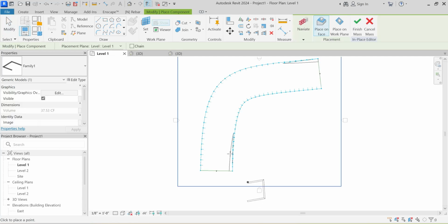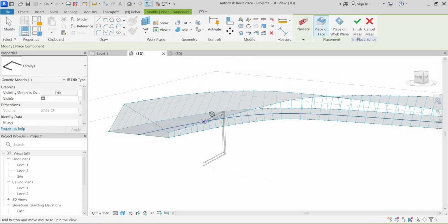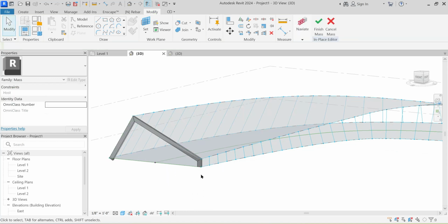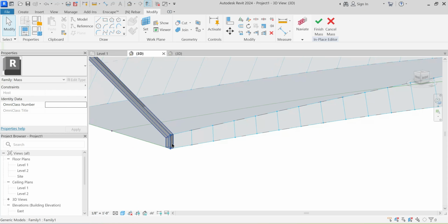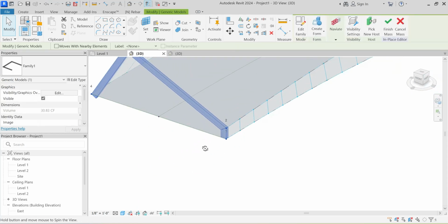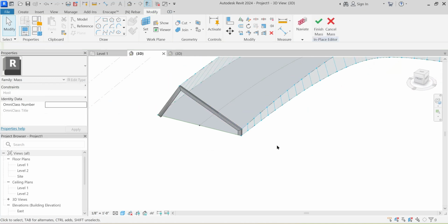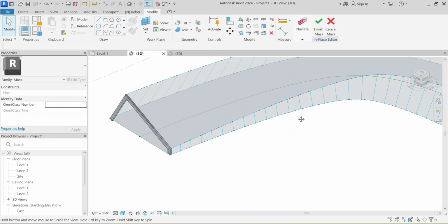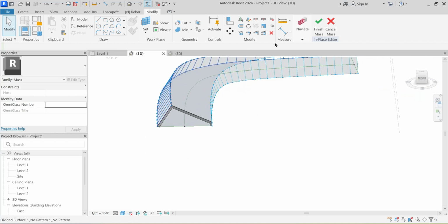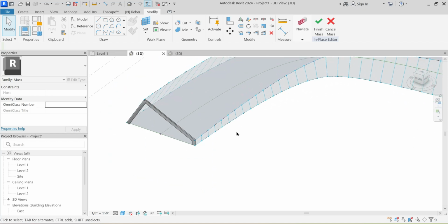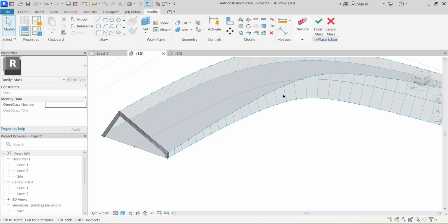Since there is an adaptive family, you have the ability to host it to points. So I will select this 1, 2, 3, and 4. Fine. Here you still see that this particular thickness, if you want, you can adjust, but I am okay with it. Now, before repeating it across all these grids, I need to manipulate this particular grid, creating one more face.